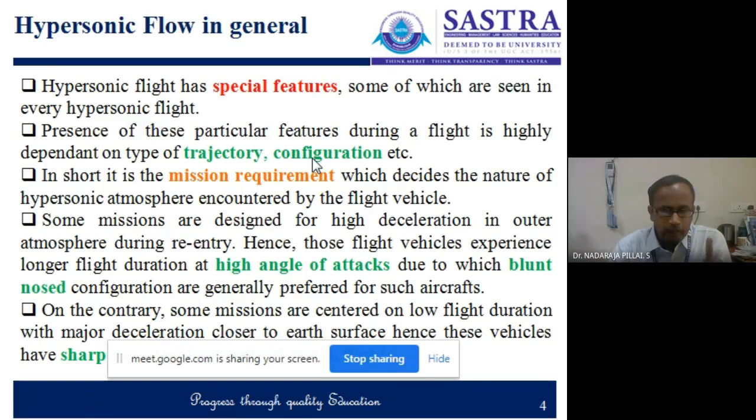From the airplane design course, you might have learned that for any airplane, the mission requirement is an important one. For example, you have designed a subsonic passenger aircraft, where you considered the mission profile: on the runway it should move and take off, then a climbing phase, then a steady level flight, then a descending phase, and then landing.